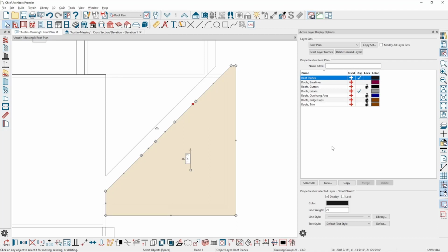Well, if they're all in a line, and in theory, these should all be in a line since I just clicked that little break guy. In my lower edit menu, there is the option, if you look in the very bottom, that says simplify, and this is anything that's got multiple points. It's called a polyline in this case. Simplify the polyline. And what that's going to do is it's going to look between the points that you have selected and say, are they all collinear? And if they are, I'll go ahead and remove them.